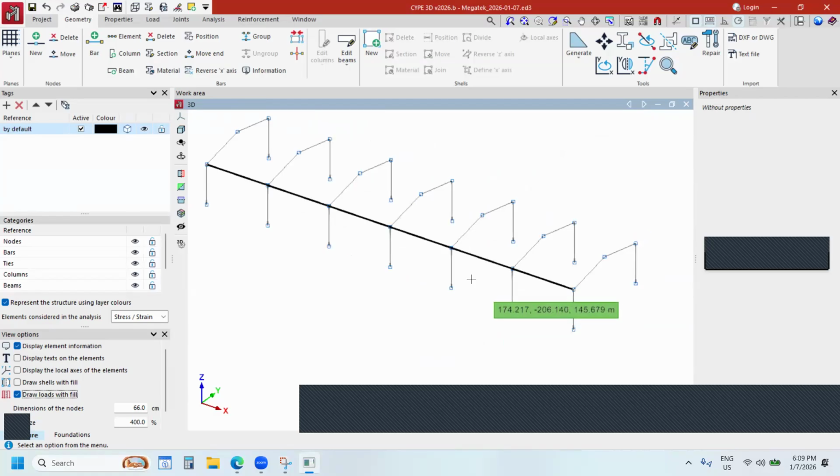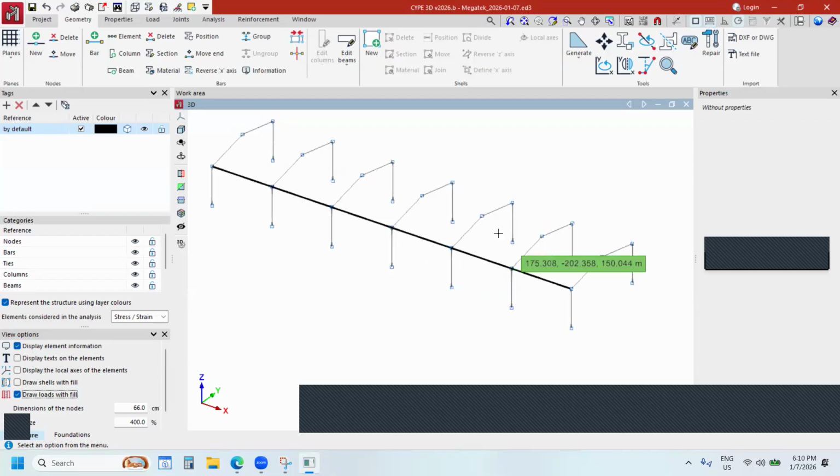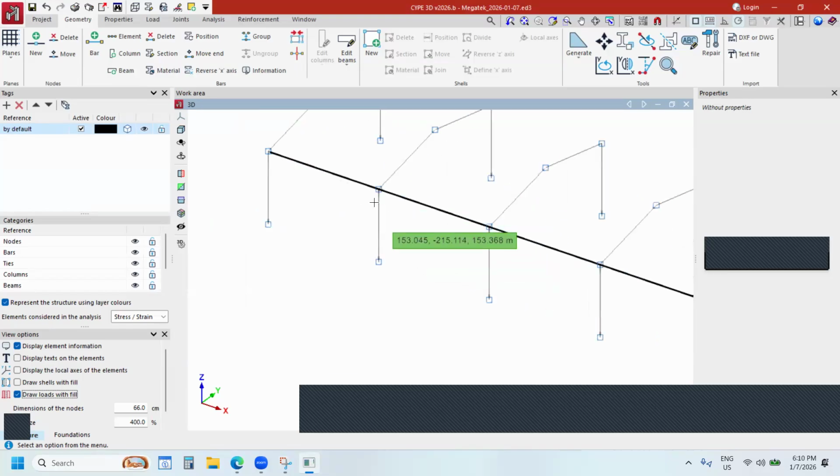So that's why you can see the color of this beam again as a bold black color. But again, we need to think about it as a designer, whether we need to keep this one as a single member, or we need to divide the member at certain locations, or maybe at each bay. So it depends on the connection type that you are looking for. For example, if we look at this column, here we know that this beam is a continuous beam, without any breaking or division.